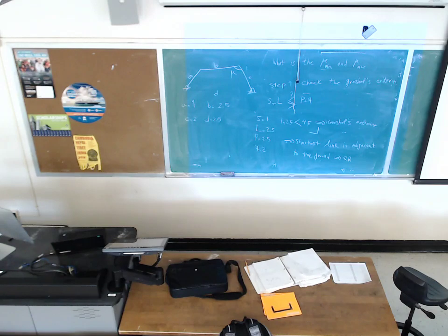So B is the coupler, and it's 2.5 squared plus C is 2 squared minus A minus D squared. A is 1, D is 2.5. Divided by 2BC, 2 times 2.5 times 2. If I do the math and find the mu min, I will find mu min is 36.87.